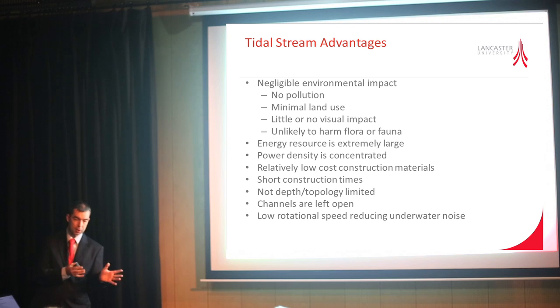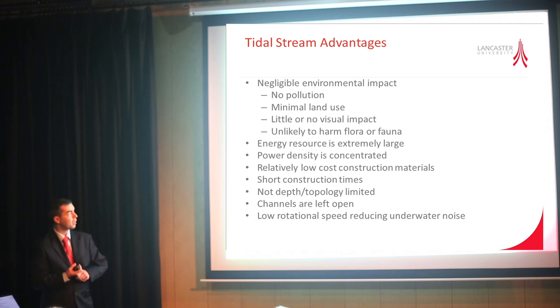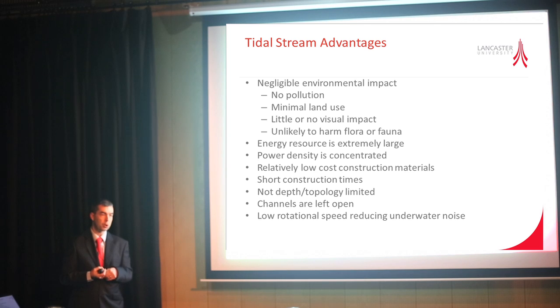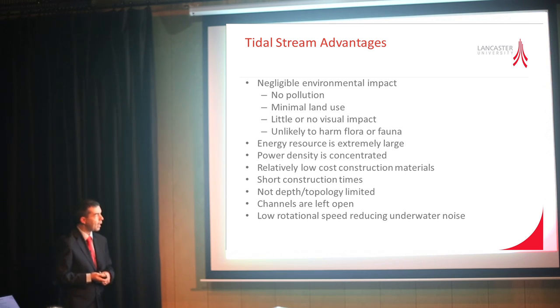So rather than build a barrage, which is very expensive, let's look at tidal stream, using the water velocity rather than the water height as an energy alternative. So much smaller in terms of construction, much cheaper, therefore for one-off devices, a much quicker return on investment in terms of the economic value of it. Potentially they can be completely submerged under the water, so it doesn't need to interfere with shipping, it doesn't need to be visually unattractive. And the channels are left open, so you're not disrupting shipping or anything else.